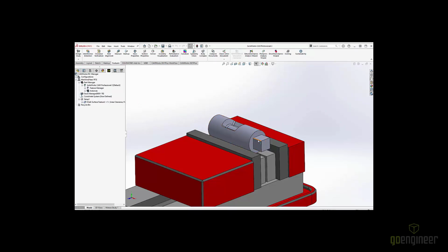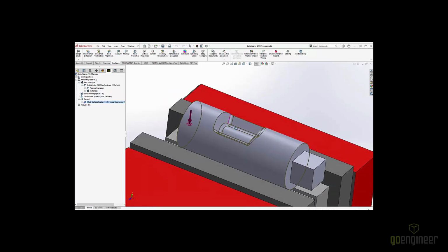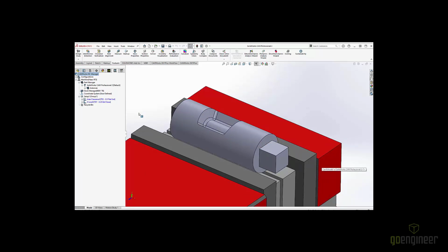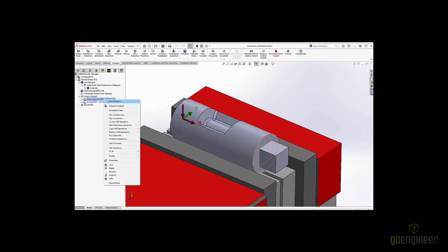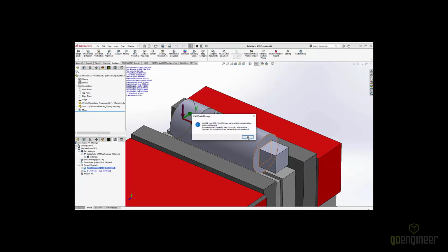So this isn't the exact same part, but it is another part file I had programmed. All I had programmed here was this multi-surface feature, none of the square peg programming. But I have that multi-surface feature program done. And I have two toolpaths over here, area clearance and Z level. Let's jump into area clearance, our roughing routine.